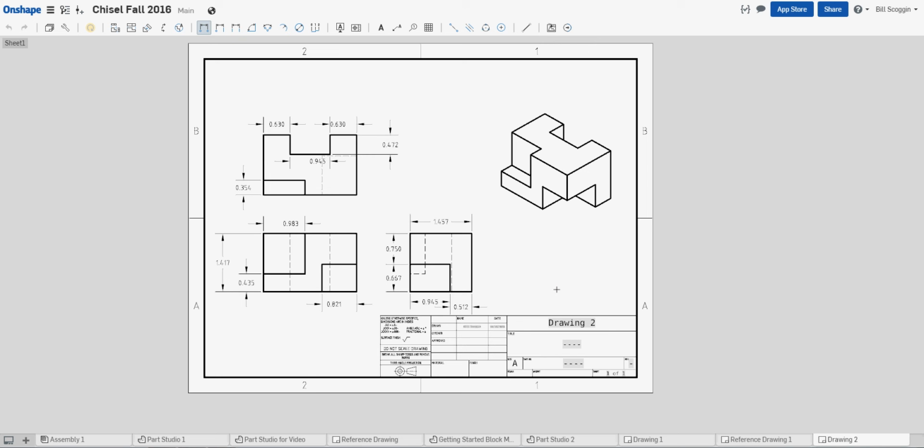And I believe that gets all of the dimensions that I need. Okay, I missed one right here. Let's get this one to here. Same thing here. I can go back, deselect this, select this one by the middle and drag it into the middle, and notice it will correct the arrows so that they don't overlap one another. And that completes my dimensioning.